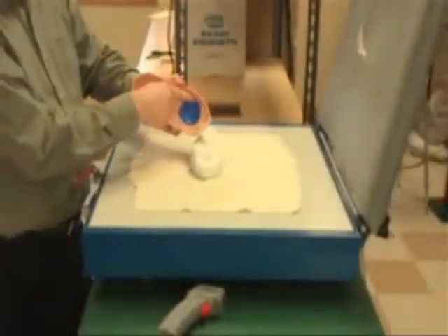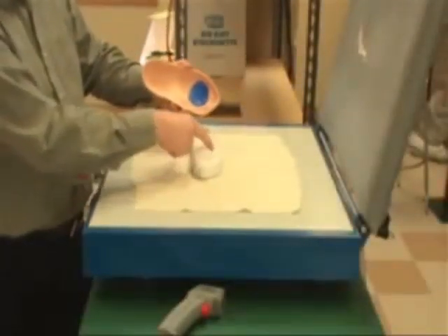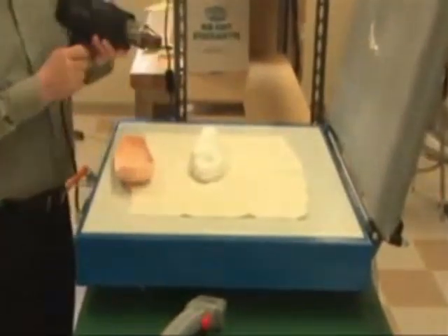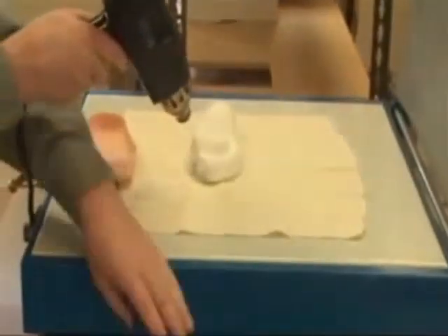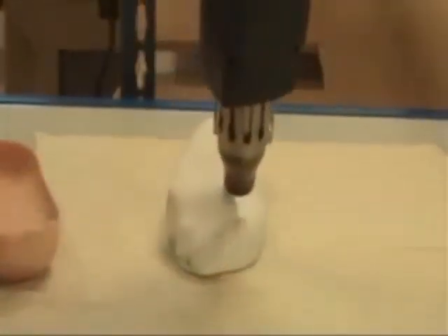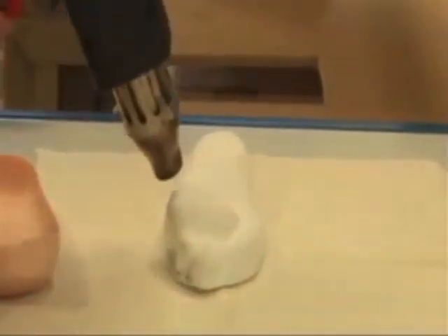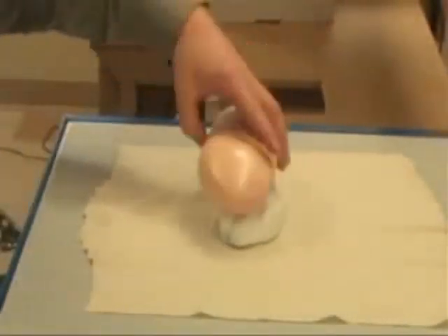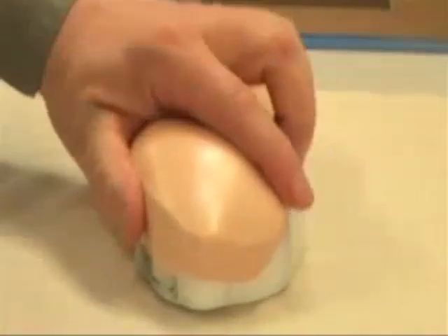This segment shows how to inlay using local heat and a vacuum press. Begin by heating the plaster mold, ideally just in the area opposite where the patch is located. Do not heat the plaster higher than the temperature recommended by the foam manufacturer. The temperature can be easily monitored with an IR thermometer.